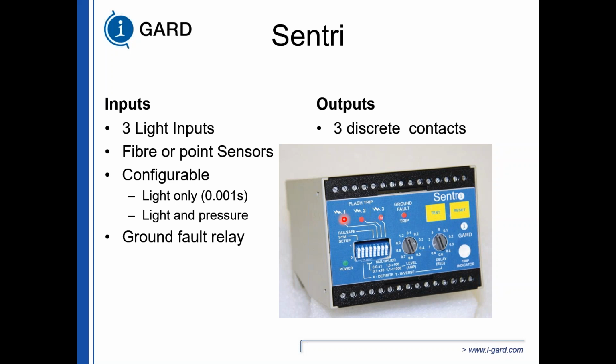And this is for metal clad switchgear. Middle compartment will be arc flash relay number 2, and we can close or open the circuit breaker in position number 2. And if you had arc flash in cable compartment number 3, you can open the bottom circuit breaker. For the main bus, we can do that with another relay.